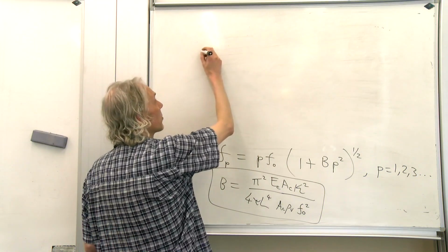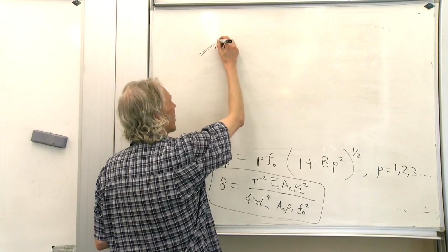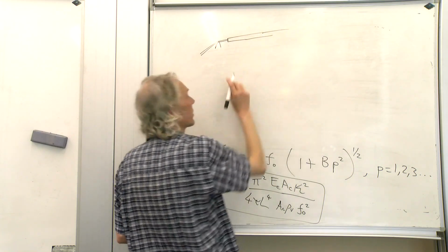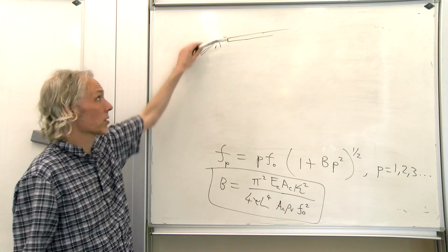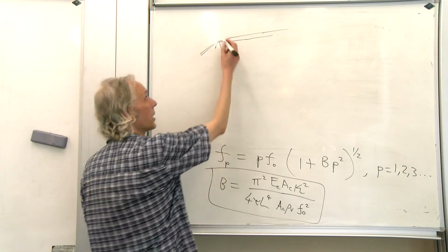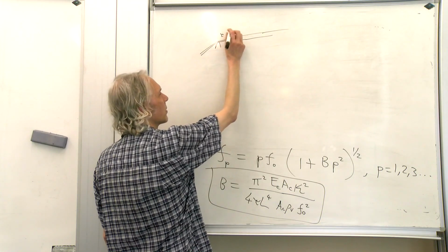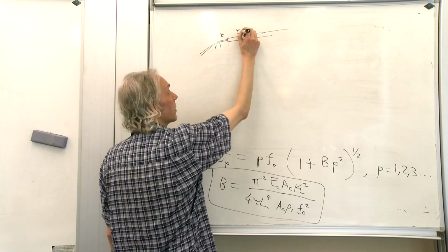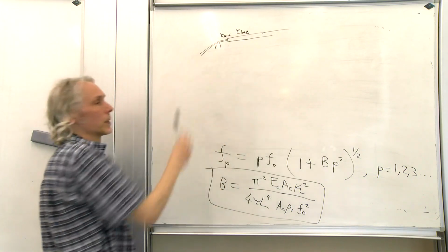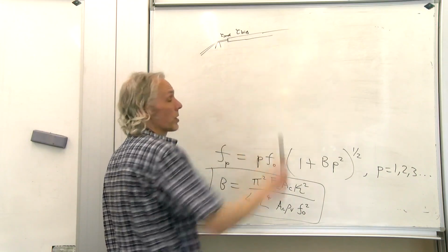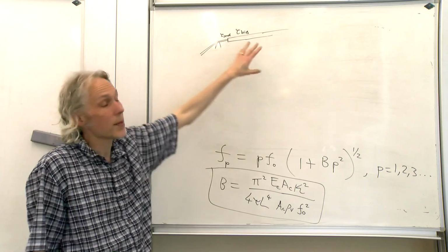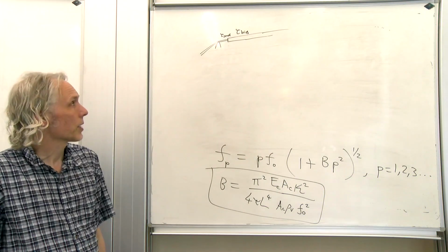So when you've got a string which is tapering, the idea is it goes over the saddle, it can bend over the saddle nicely, and then the string gets thicker for the rest of the sounding length. And that helps with getting the string to actually bend over the saddle. So that's called a taper, and it's got a lower mass here. So tau here and tau here. That tau is bigger, and that tau is smaller. Okay, so that's just adding extra layers of winding underneath before you put the layer winding on the top. You can make a tapered string. Okay, so that's something you can do.